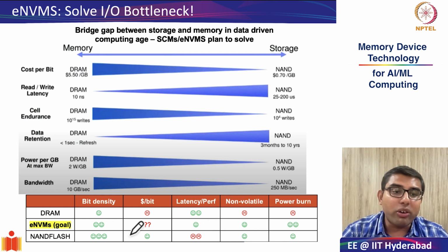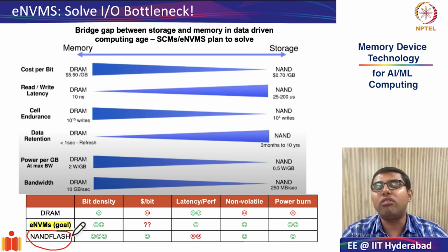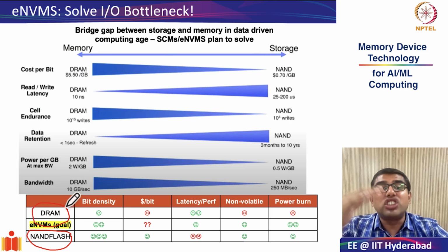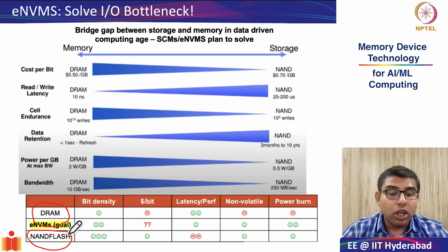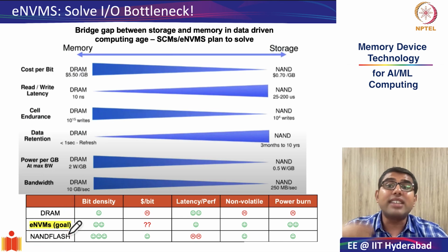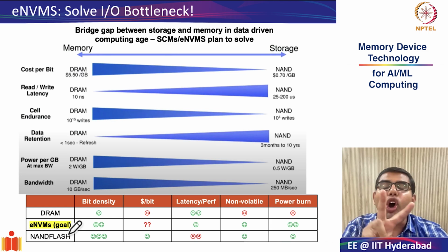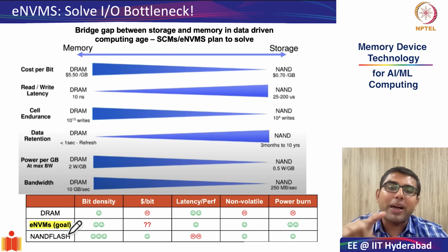Why this is possible is something that we should think about very carefully. At the system level, remember, NAND flash was completely sequentially driven storage, whereas DRAM was random access, right? And that is why the sequential access also caused a lot of the latency issues. The goal in eNVMs, as you will see from their names, RRAMs, MRAMs, PCRAMs, is that they are all RAMs, random access memories.